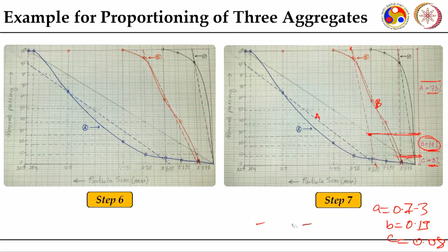Now, for different materials, when you do soil stabilization also, in those cases also you do this blending of different materials together to arrive at desired proportioning. So, this is the initial step which we normally do whenever a mix design of these unbound granular courses is to be done, that you look into the blending of the aggregates, in what best manner different stockpiles of aggregate can be blended to achieve the desired target gradation, which is suitable for use as a sub-base course or a base course, and under that particular also as different gradations are specified by IRC and MORTH. Thank you.